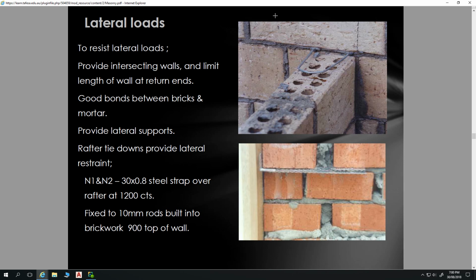that rafter with enough force, because that rod goes through the brickwork, it has to take this brick which is above it. That brick will take those two bricks above that. Those two bricks will take the three bricks above that. Those three bricks will take, and you'll end up taking this cone-shaped piece of wall with you as you lift it up. So that's why the further you embed this rod, so that's 900, we embed it down to 1200, you end up taking that much brickwork with you if you try to pull it up.